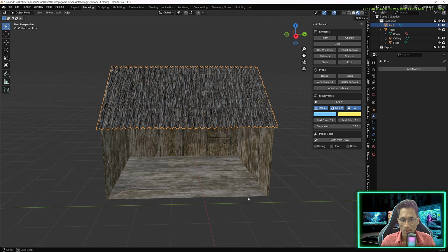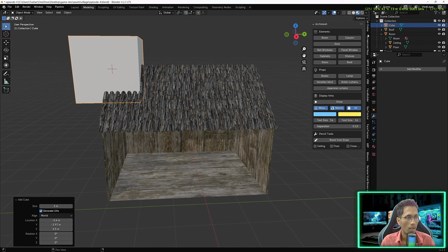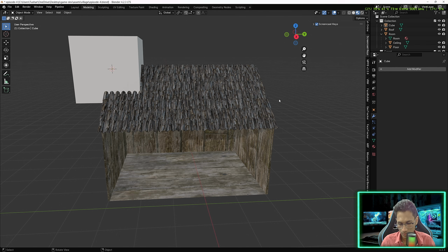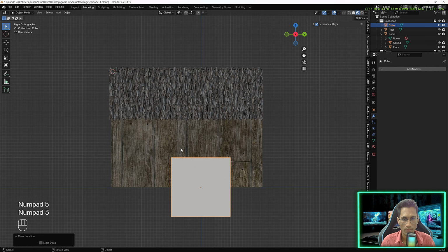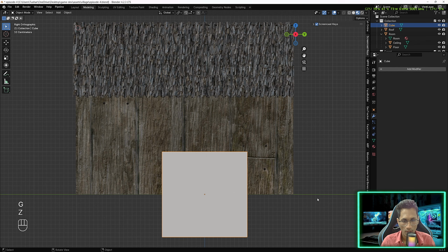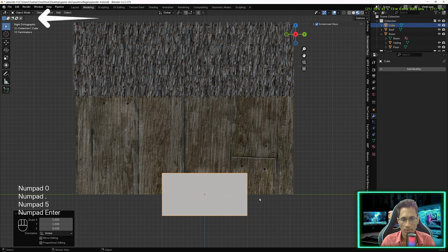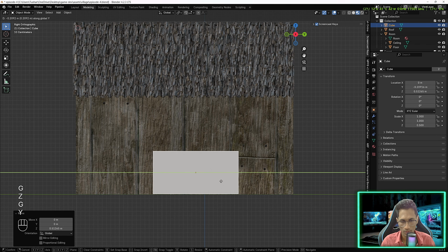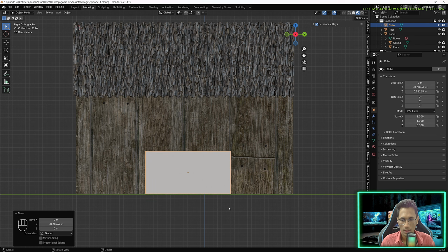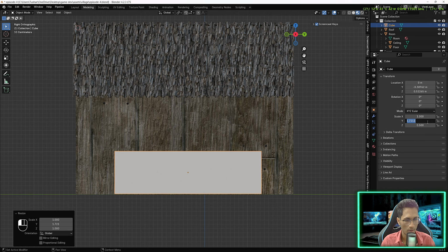All right, so we are in the Blender now. Let's do it. So Shift A, Mesh, Cube, and let me turn on the screencast. Select this cube, press Alt G to bring it in the center, 5, 3 to get it in the front, and then S, Z, and go by 0.5. Go in the properties, G, Z, and we'll take it here in the center. And then we will scale it in the Y direction. So let's go for something like 1.5, or let's go for 2.